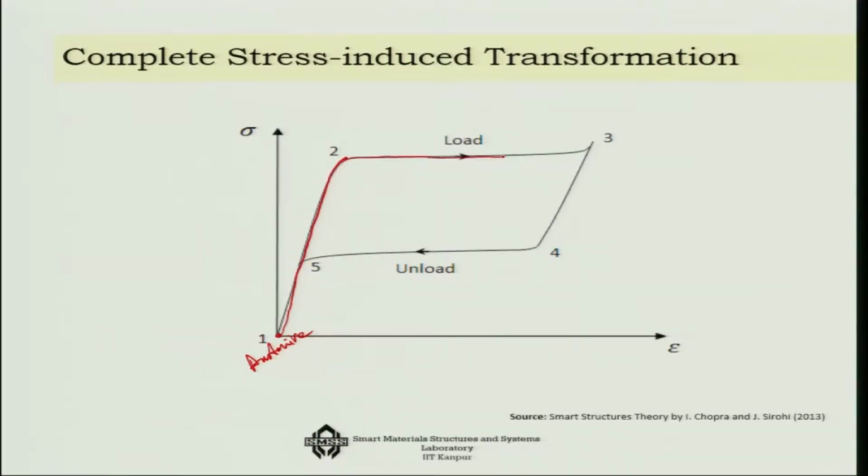This is stress-induced phase transformation, and I am going back to the martensite phase, and then from that phase I am reducing the load again, and if I reduce it, initially it is once again elastic, and then the huge change, and it comes back to number 5, and then if you further reduce it, it will be at that austenite stage itself.